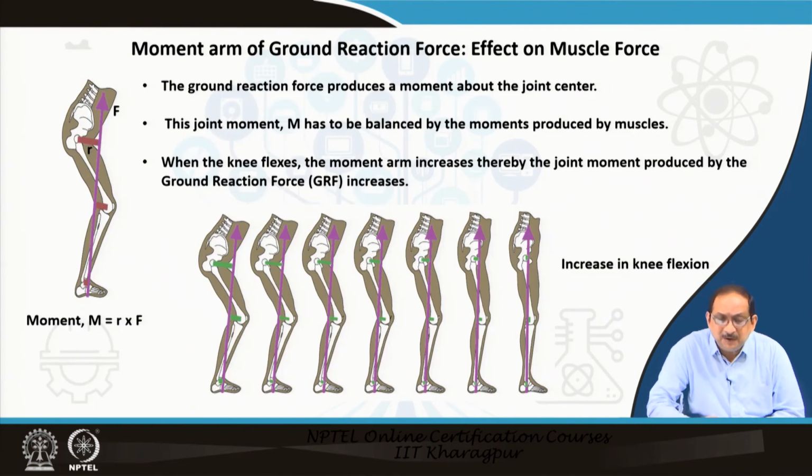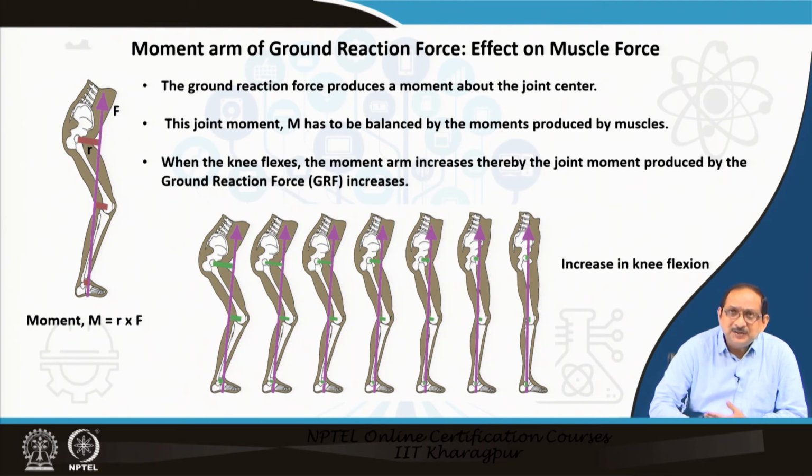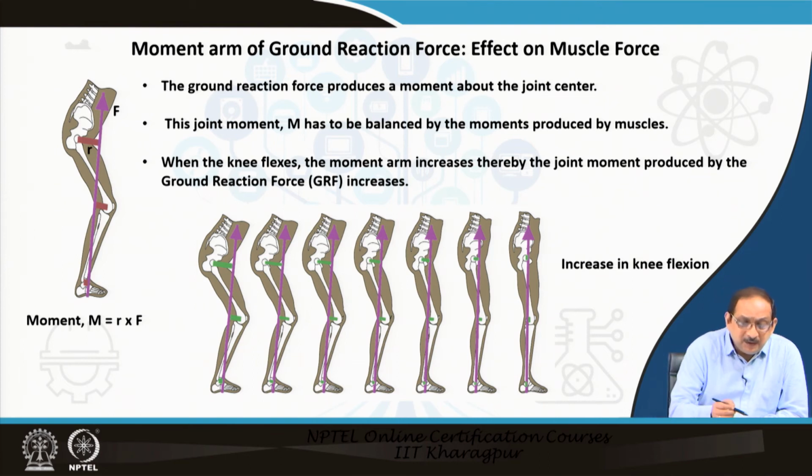Now, let us discuss the moment arm of ground reaction force and its effect on the muscle force. We had discussed this earlier, but I will be brief in discussing the contribution of ground reaction forces in generating the muscle force for a particular posture. The ground reaction force actually produces a moment about the joint center.